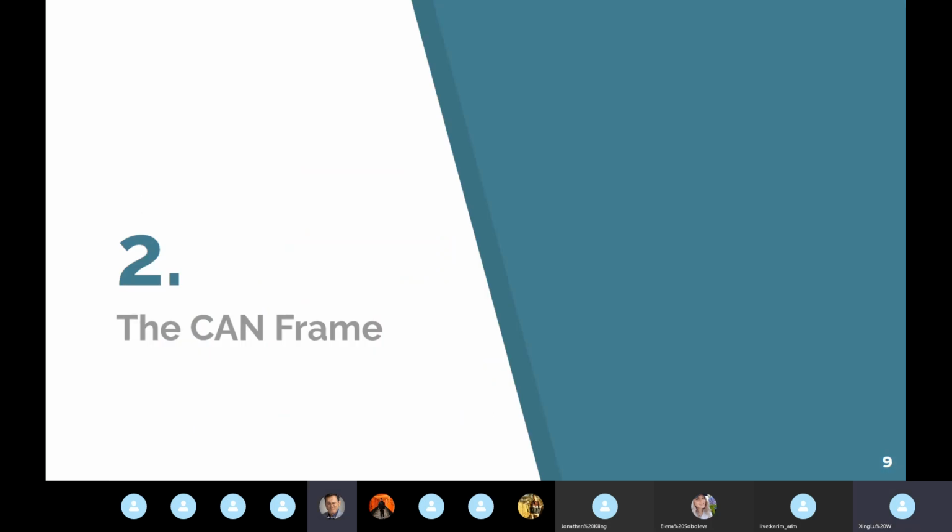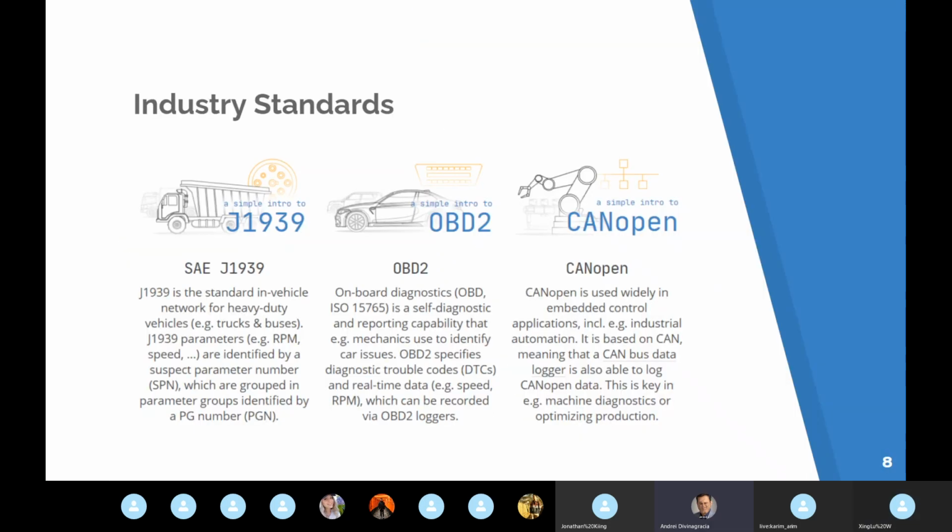So I guess we do OBD2 then? Our CAN standard is OBD2? Actually, putting ours into one of the standards is really overcomplicated, mainly because the TMS 570 doesn't have the software stack to support it. I would have to write one myself, and I'm not going to do that. That's going to be overkill.